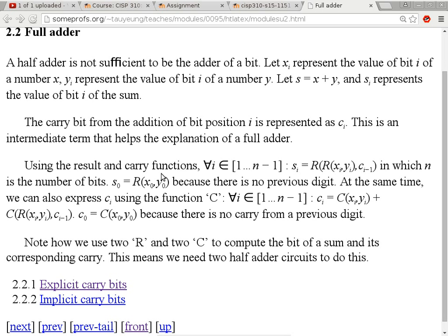We have two transistors on the top that are in parallel. Actually, these are p-channel MOSFETs, so the bar goes on the other side. So we have two p-channel MOSFETs here. They're in parallel. This is the output, and then we have two n-channel MOSFETs in series down here, right? This pin and one of these pins hook up together. This pin and this pin hook up together. This is one input. This is one input. This is my output. This hooks up to VCC, and this hooks up to ground.